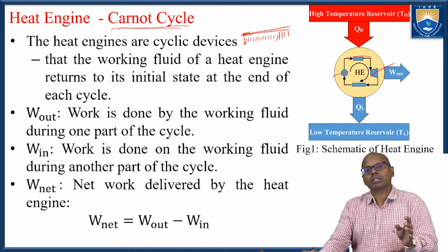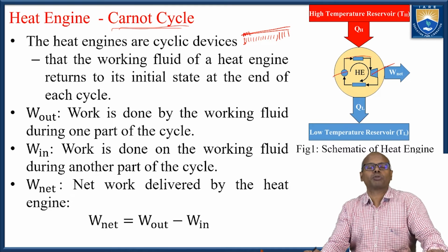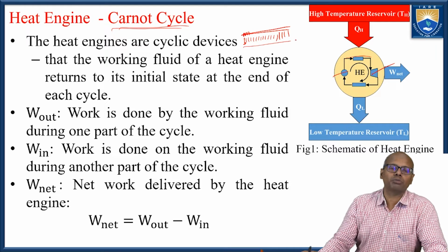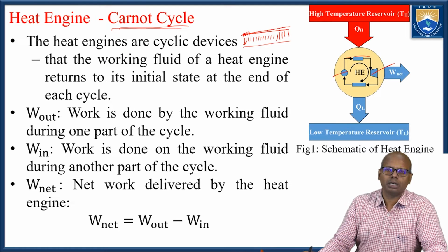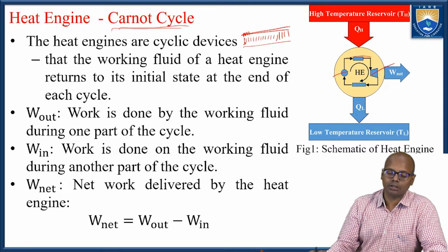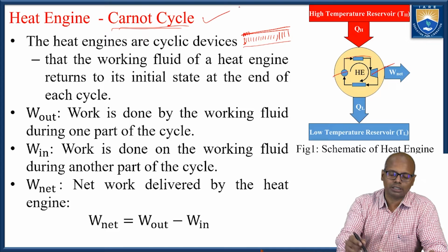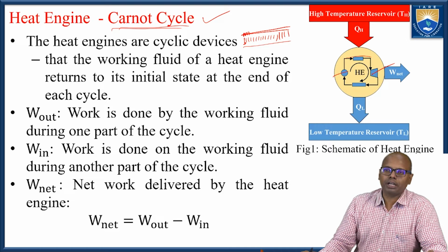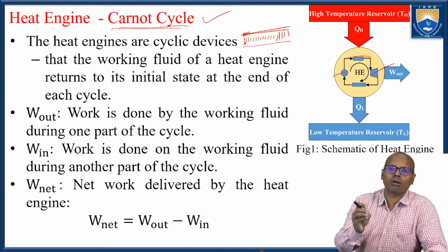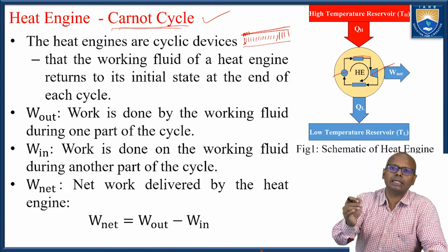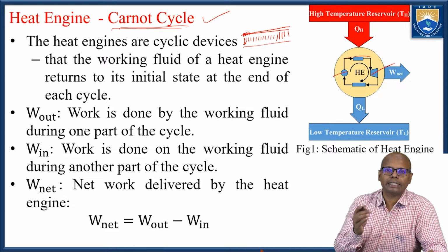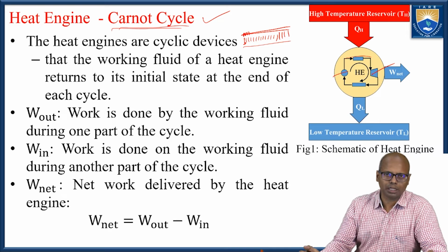But ideally speaking, this kind of process is not possible. These are theoretical or hypothetical processes, and they are called reversible processes. The reversible processes taken into consideration by Carnot in his cycle are called the Carnot cycle. Now here I said two constant temperature heat addition and rejection, and two constant entropy work processes are happening here.